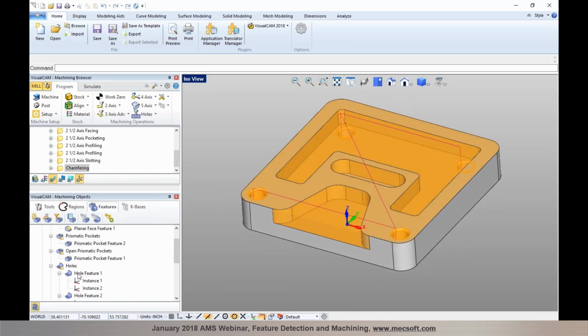In order to include the drilling features, since the hole features and the milling features are different feature types, in the case of hole features, you could have through holes, blind holes, you could have holes with a counterbore or holes with a chamfer, which could be like a countersunk hole. So those are identified as a separate category of features, like hole features. In the case of milling features, you typically have either closed pockets, open pockets, and they all can be programmed as a milling feature. That's why we differentiate between holes as a separate feature type versus the milling features.